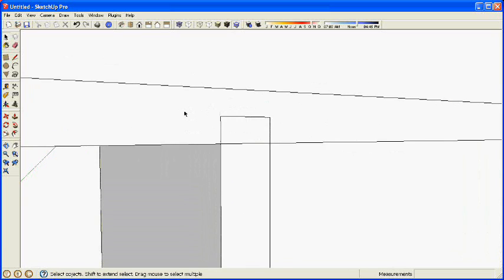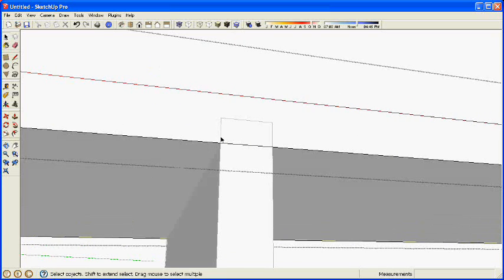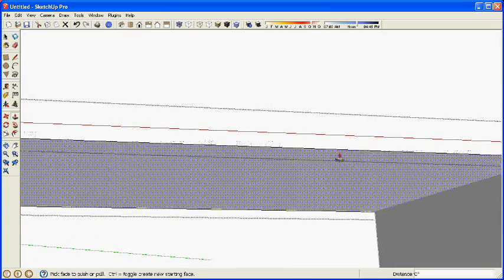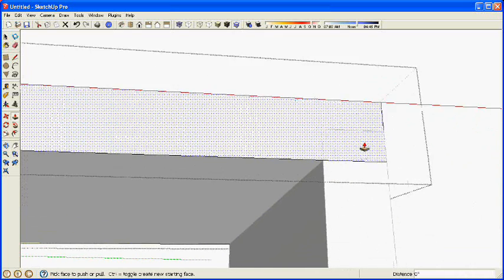While we're up here, let's go ahead and we'll cut the dado for the center panel. So again, a rectangle, just tracing that end, and I'll double click this time with the push-pull tool, and that just cut the dado there. And we've got one last rabbet to cut.